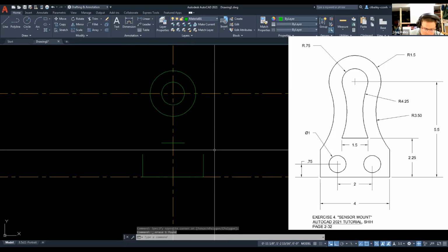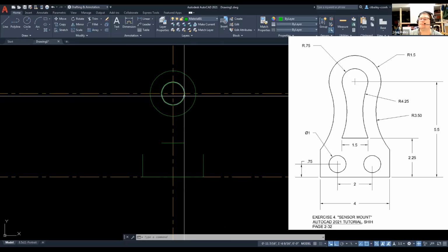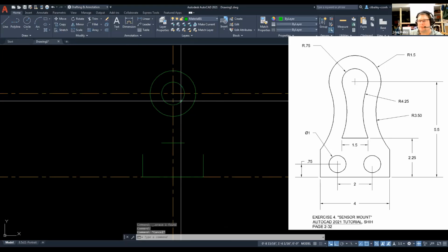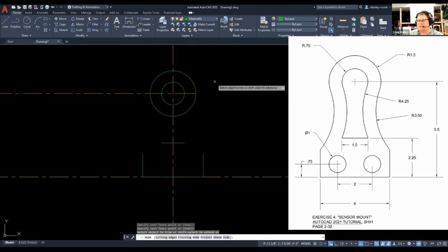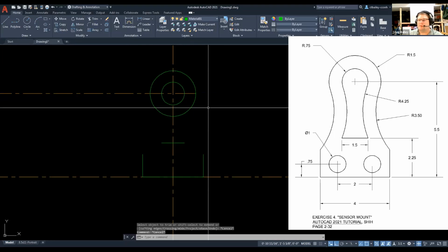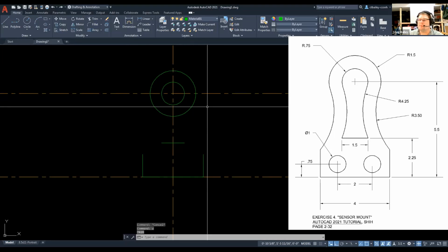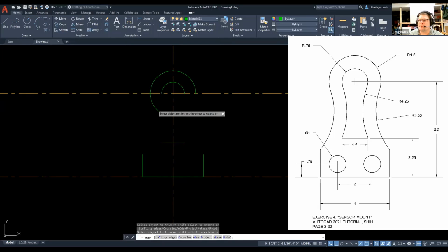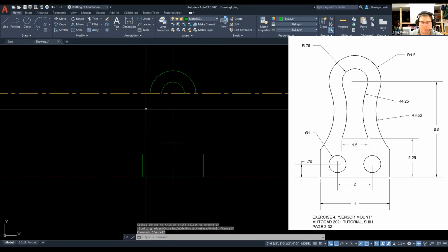And so now the rubber hits the road. We need to do a reverse curve, with the inside reverse curve having a radius of 4.25, and it has to be tangent to this center circle here. And so I'm going to just start this. Oh, I didn't mean to do that. Undo. Clean these bottom halves of these circles off. All right.